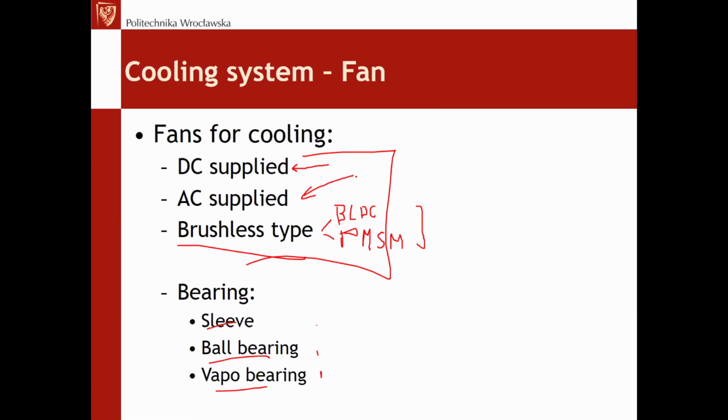the AC motors. So no brushes means less noise, no moving elements, no moving contacts. That means far higher reliability of such motors, lower noise, better torque and so on. The problem with the brushless type is that the full control is given to the microcontroller. So a dedicated MCU is usually required just to drive the brushless motor.